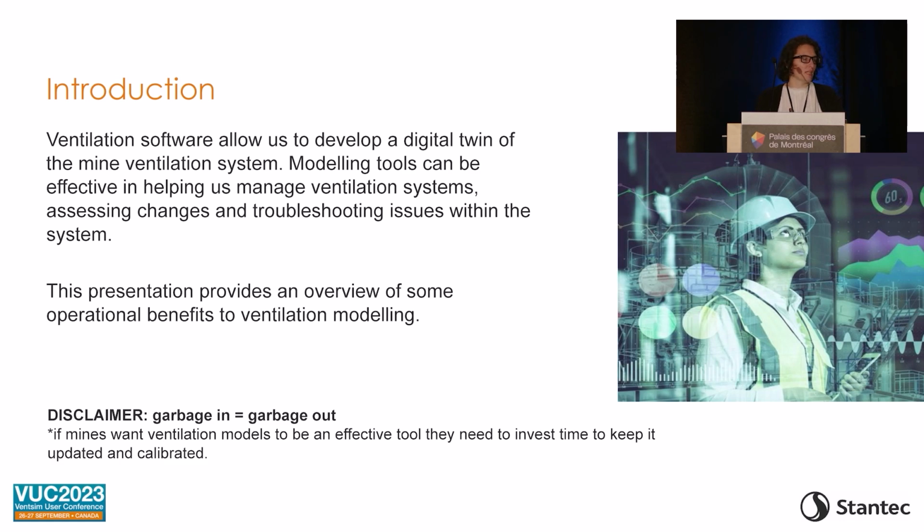There are obviously a lot of benefits in using Ventsim, and I'll just cover a few, but there's a lot more. And the disclaimer is that with ventilation modeling, it's garbage in equals garbage out. So we need to make sure that when we're using Ventsim or any ventilation model, we're giving it good parameters and calibrating the models to make sure that we're getting information back that makes sense.